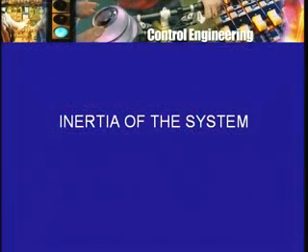And what is it that we ignored earlier when we looked at our motor problem? Because of steady state considerations, that is because we said that, all right, the torque will be constant, the applied voltage will be constant. So after some time, the armature current will be constant, the motor speed will be constant. And because of this, we made some simplifications, or we simply ignored or deleted some terms in the equations. These terms were arising out of some kind of inertia of the system.